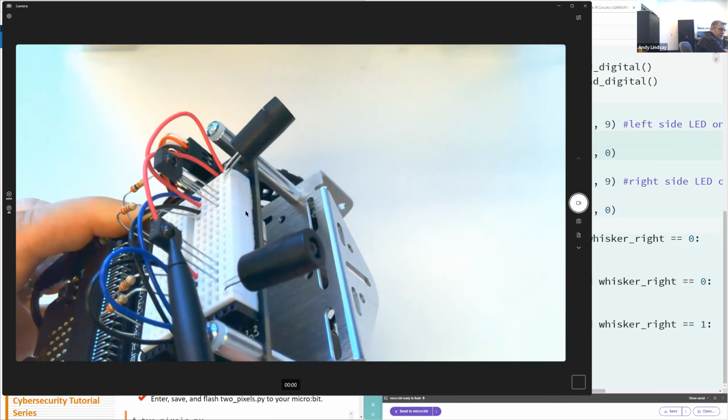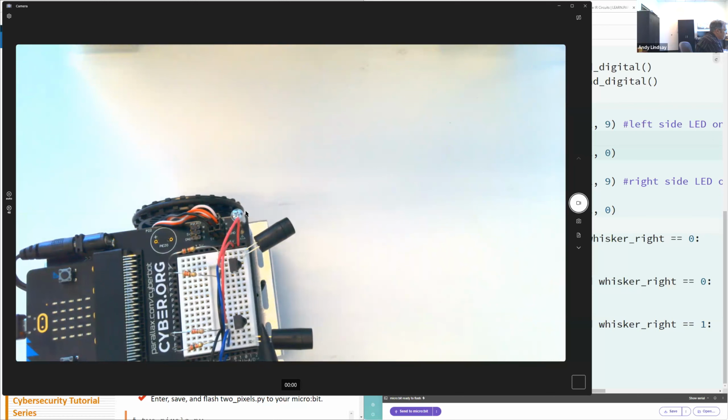That needs to be facing the same direction as the tubes are. It needs to be facing essentially forward on the robot. So the bump needs to be on this side, not over here. Absolutely not facing this direction. So each bump on the little square infrared receivers has to be facing forward. So check that.